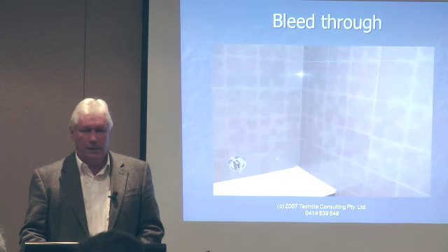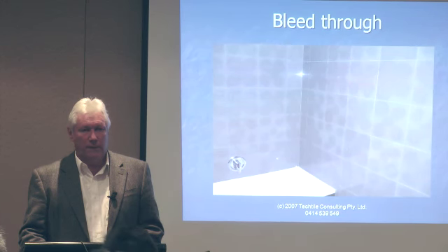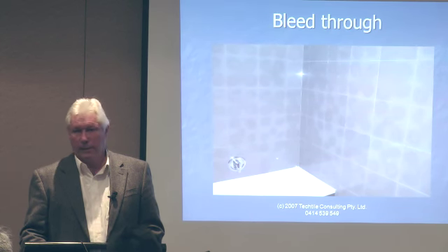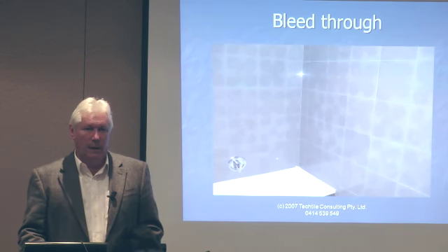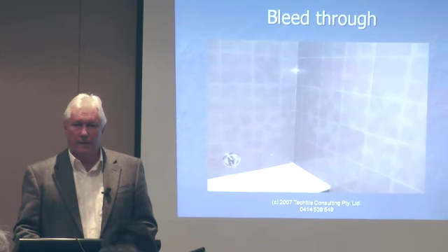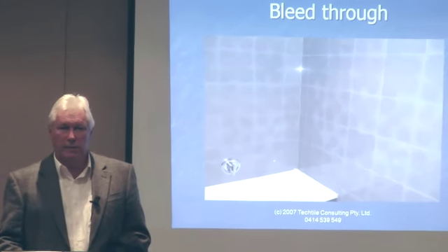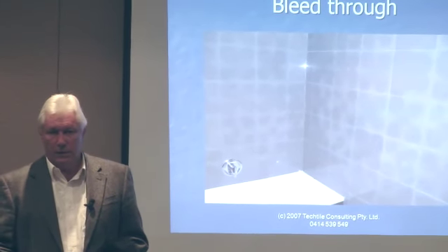Now, the reason that it didn't become evident straight away was because the water would come through and change the whole colour of the tile. And so the whole bathroom would have gone a bit darker and nobody would have noticed anything. Then as things have dried out, the calcium hydroxide that's been coming with the water and the cement in the mix has moved through the stone and into the little pores in the stone.